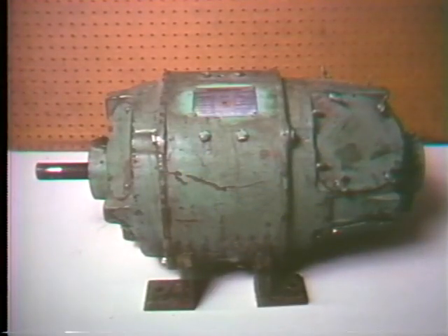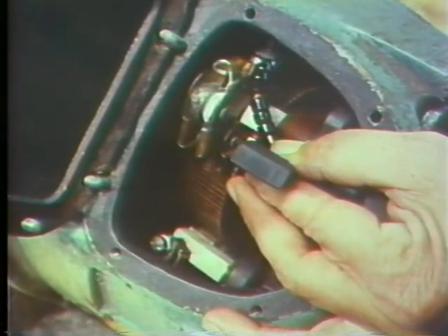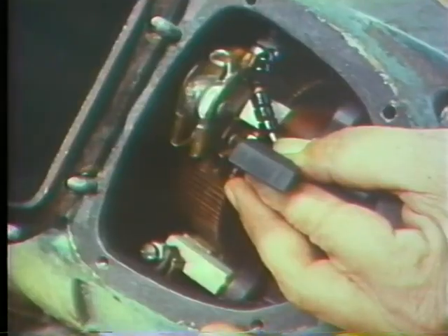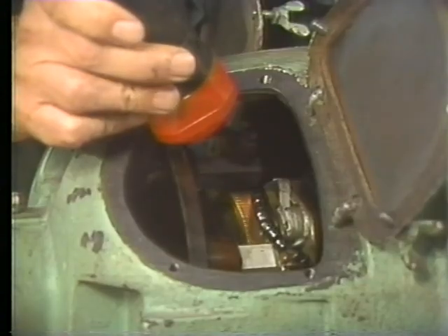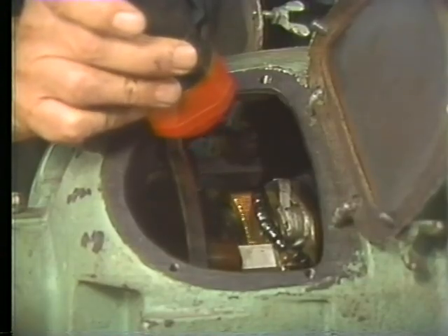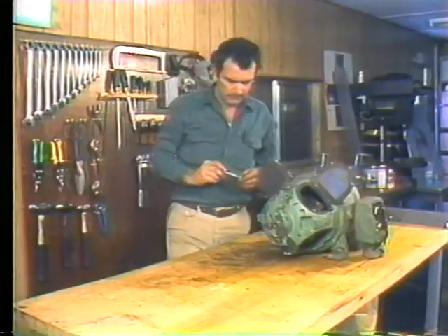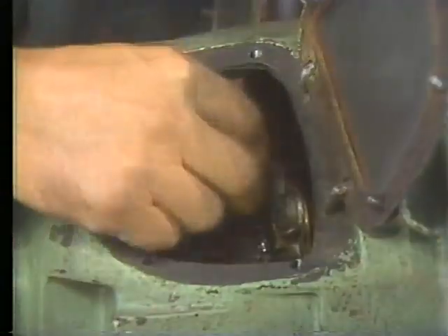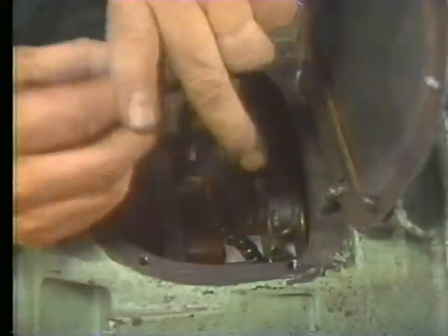We'll mention the kinds of problems you'll be running across first, and then go on to cover what you can do about them. Let's start with the commonest source of trouble, and the one that's easiest to correct: the brush. As the brush slides on the commutator, it's going to wear, and as it does, carbon dust from the brush will cover other parts of the motor. That leads to problems. Any brush is going to wear down eventually. You've got to replace them when they get too short to do the job.